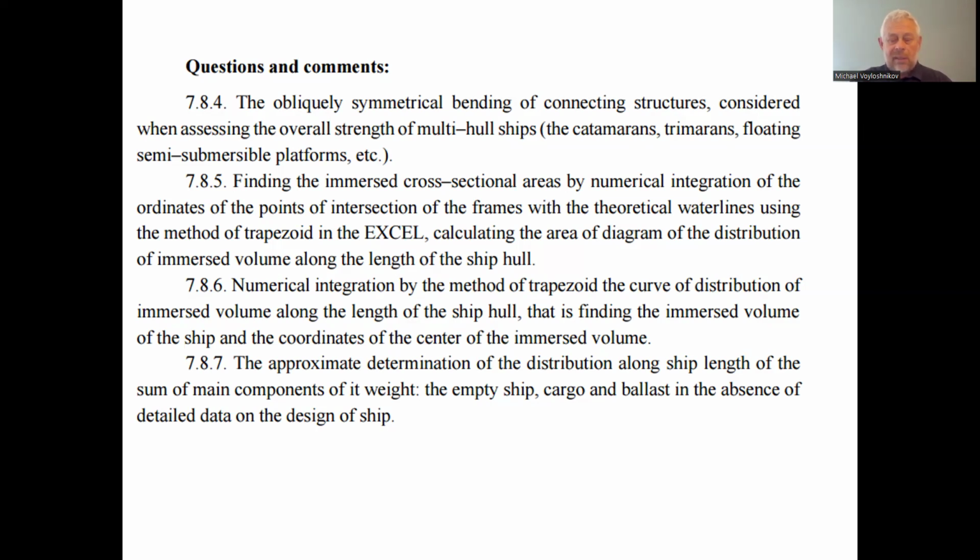So we can consider the ship load consisting of parts, not only cargo, sorry, but the load of the cargo and of the ship empty itself. So we consider the variable loads as the fuel, as the ballast. We consider the cargoes. We consider the empty ship weight, lightweight so-called, and we consider the lightweight consisting of the parts. Could be the part of the ship hull itself and the weight of the superstructure. And we have to adopt this always to the segment of the ship length.